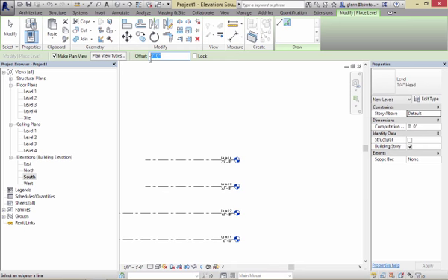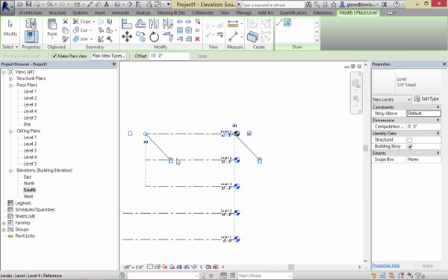So if I want the next one to be 10 feet, the next one to be 10 foot higher, I'll put an offset of 10 feet in there. And now we're ready. So here's how offsetting works. I come over this other level, I'm just slightly above it, not quite touching it, just slightly above it. It'll suggest, hey, I can draw another one for you at this location. That's 10 feet away. If you like that option, just click and it'll put a second one there.